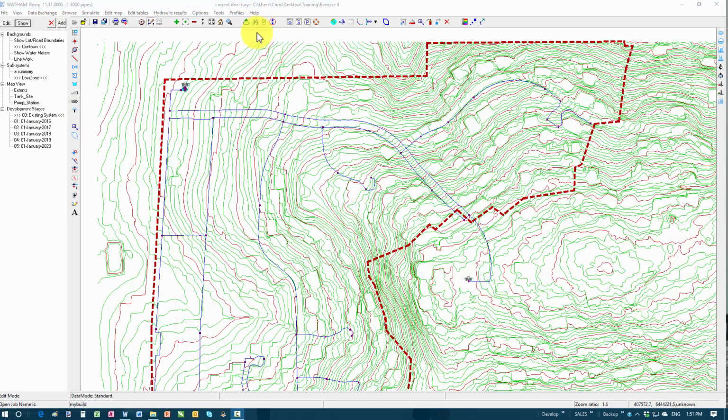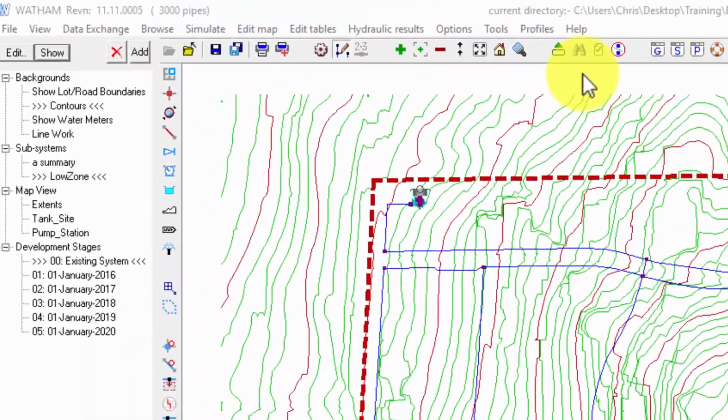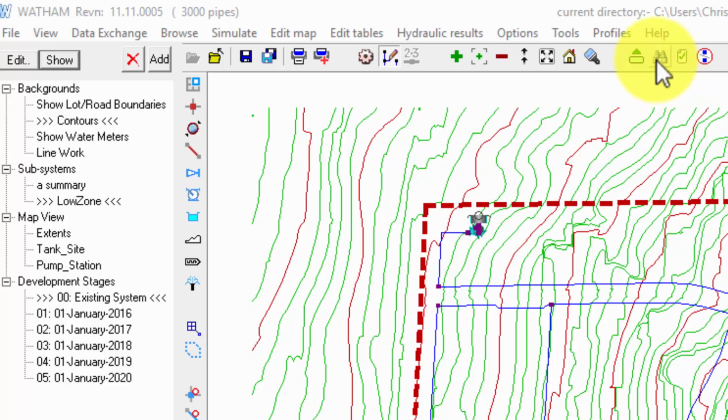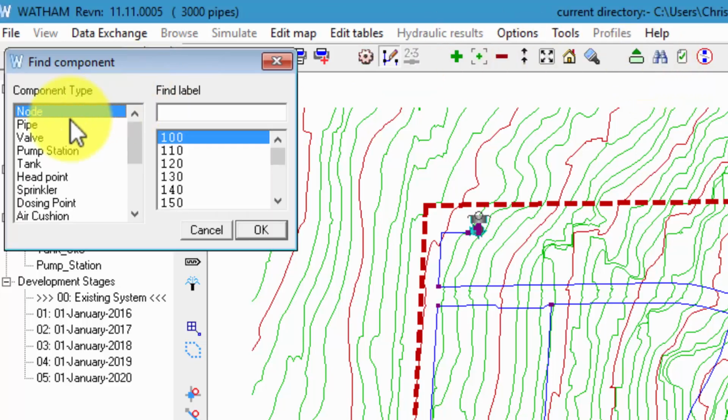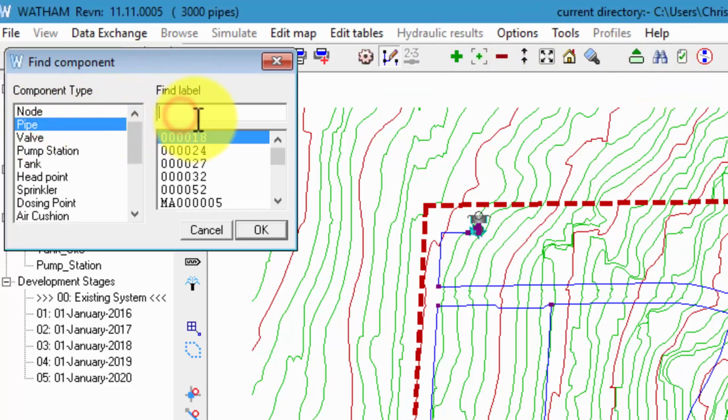Now we are going to look at that one pipe where its vertical profile needs to be manually entered because its pipe laying condition is follows plant isometrics. In edit mode, find the pipe labelled station out.